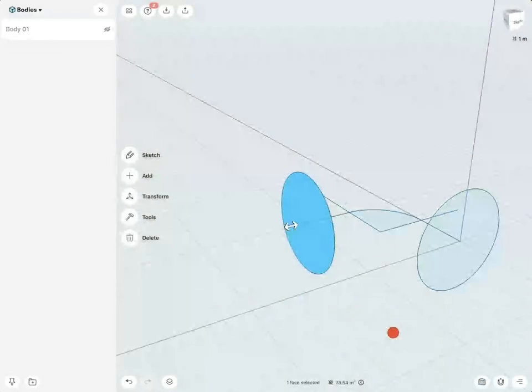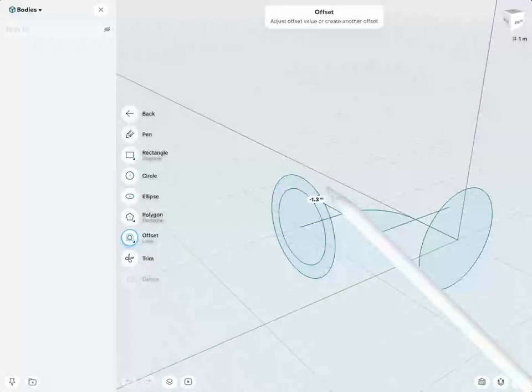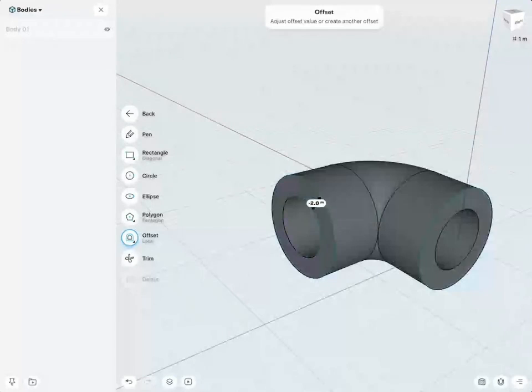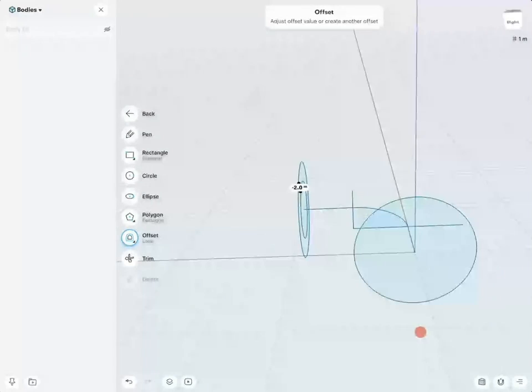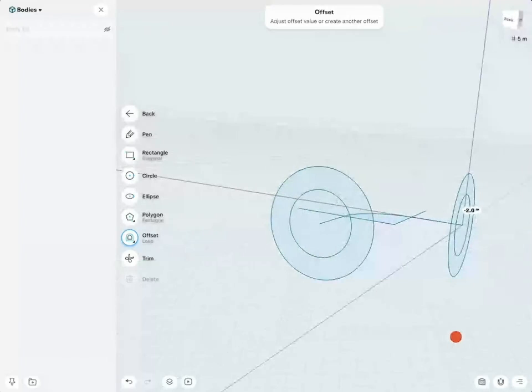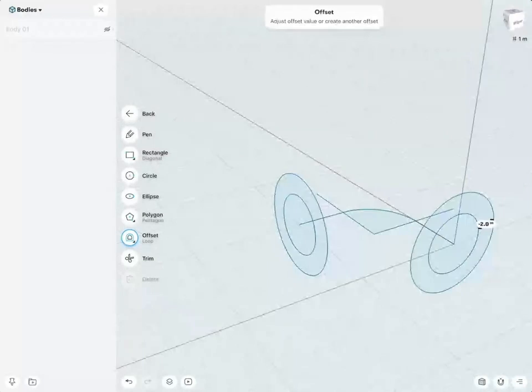This is where our existing sketches here will be very useful. We go to sketch and offset. This one, I go in by 2. Let me double check. Yep. And then we do the same here. See, when we do the offset, we do not need to switch to the individual construction plane, because this circle is flat. When we do an inner offset, it is aligned on the same construction plane. Very good.